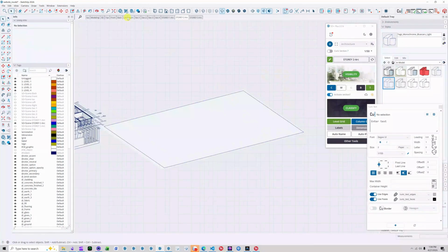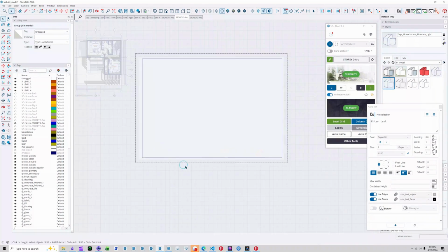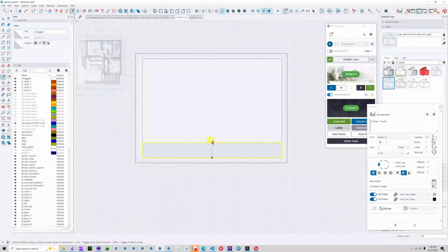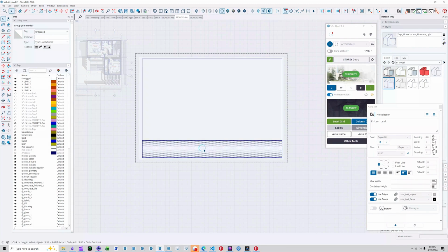Next, I'll draw the margin on the side. Let's do the bottom margin first. I'll just draw a horizontal guideline like this. This is how I work. Once that's done, I'll delete this line. Then I'll select the face, press the scale command, and enter about 5,000 millimeters when scaling. Press enter and millimeters. Right, it's just got bigger. This is 4,000 millimeters. Right, that's done.